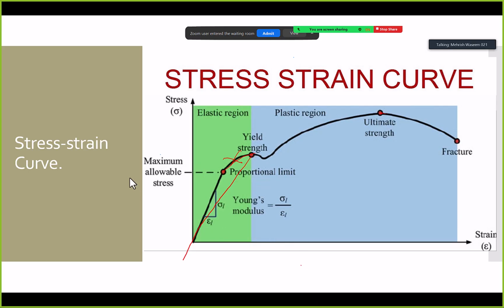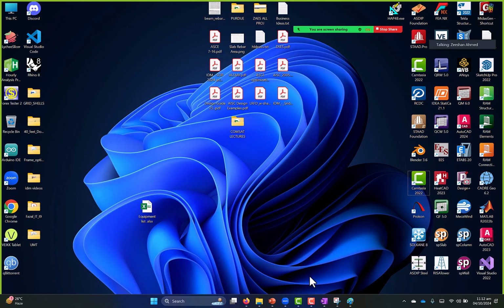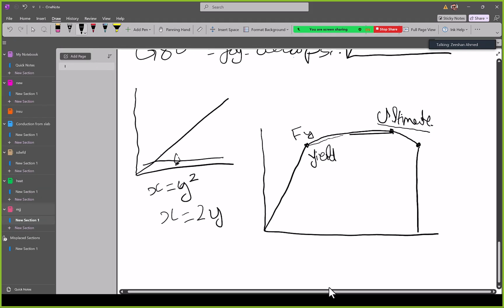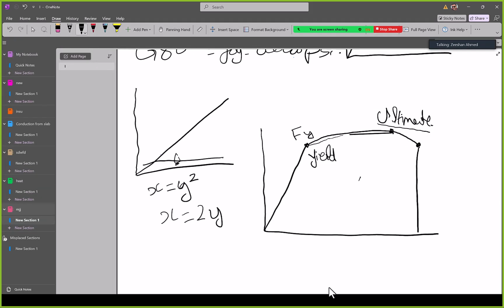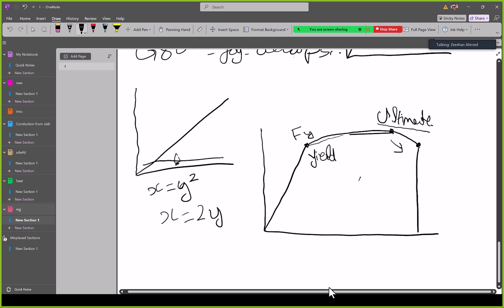सर, हम ग्राफ में इसको कैसे आइडेंटिफाई कर सकते हैं अगर लेबल ना हो? आपने अल्टीमेट के कर्व पॉइंट को देखना है. आपने इसके कर्व को देखना होगा. When it is going to be dipping down, when it is starting to go down, this is that point, जहां जिस पॉइंट पे ये यूं सीधा आ रहा था और डिप डाउन हो रहा है, that is ultimate. जिस पॉइंट पे स्ट्रेट लाइन कर्व सीधी होना शुरू होगी, that is yield point. जिस पॉइंट पे ये लाइन एकदम से एल्बो बना के नीचे आ गई है, that is breaking point. समझ आई? That is how you identify.